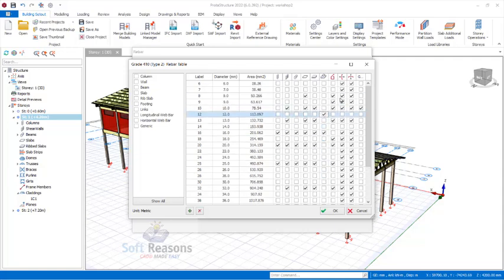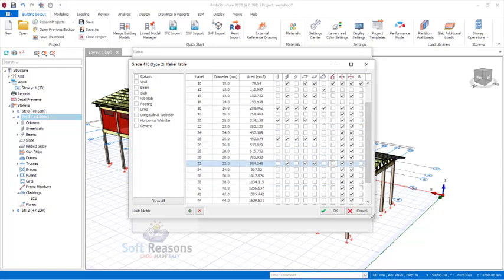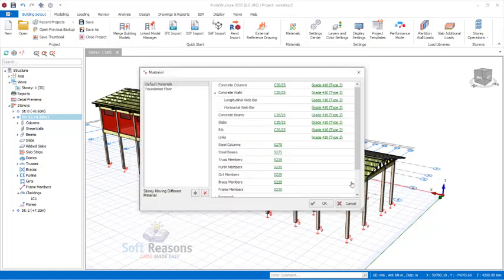Okay, so over to the links, we will be considering 8 and 10. Alright, so you get rid of other links provisions or the shear reinforcement successfully. Alright, so this is how you select your reinforcement material. Click on OK options and then OK again, and then finally you have to OK.